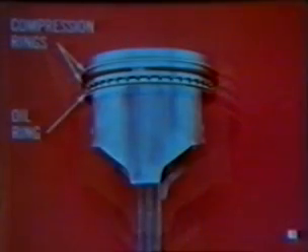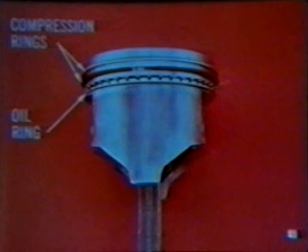Most pistons are made of aluminum to keep their weight moderate. Because aluminum expands greatly with heat, steel struts are usually cast into the piston to control the expansion. The top of the piston has ring grooves machined into it. Piston rings are installed in these grooves to seal against the cylinder walls. That way, the piston can operate with some clearance for lubrication and heat expansion. Most engines will use 2 compression rings and 1 oil control ring on each piston. A 3rd compression ring is added on some heavy-duty truck engines.